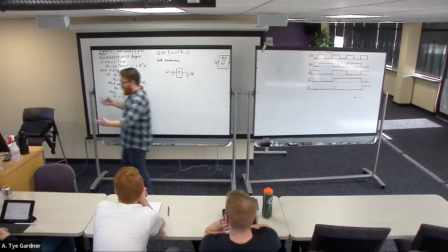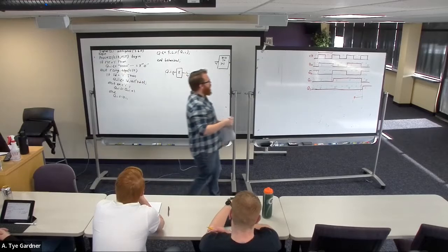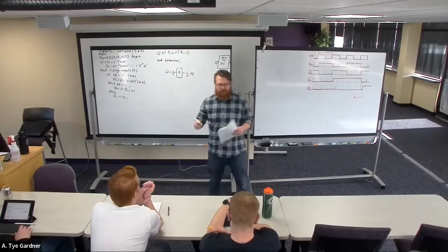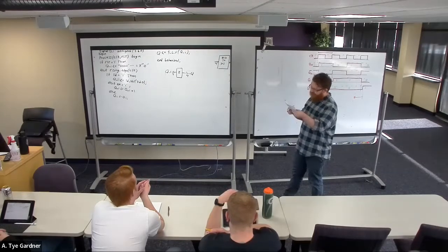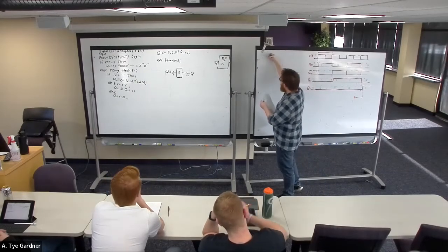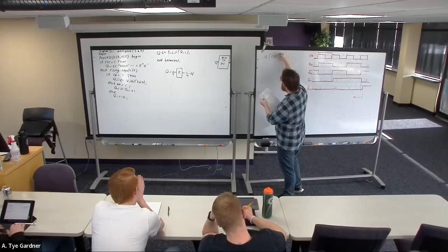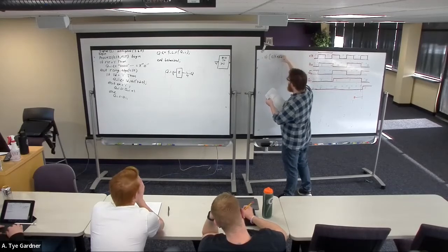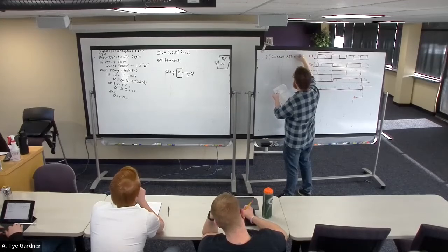Just in case you see this code, I will never write it this way, but if you're looking at online references, instead of the if rising edge of clock, you will see it written: if clock'event and clock = 1.